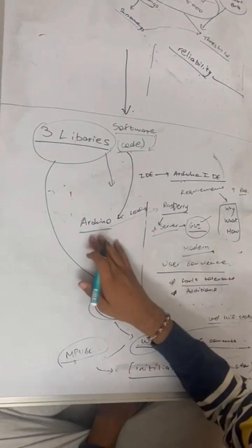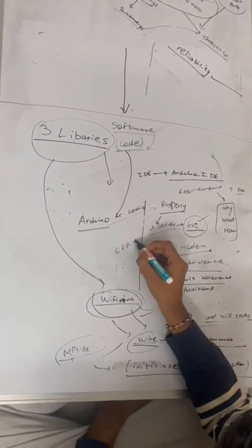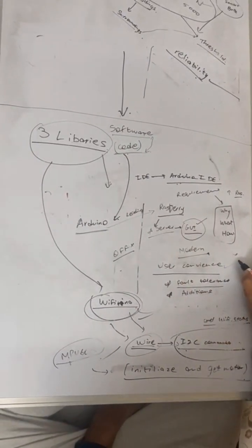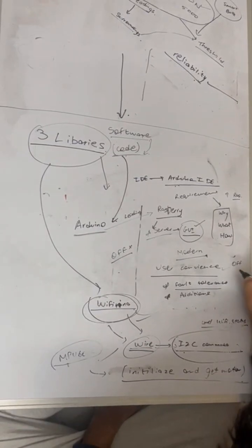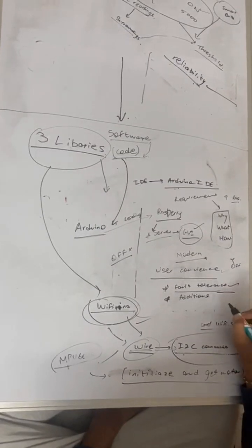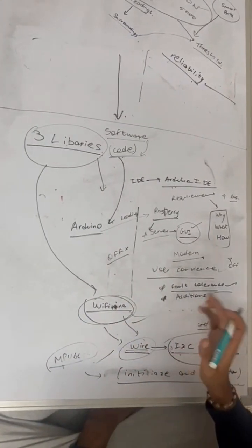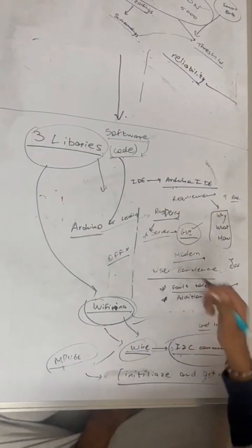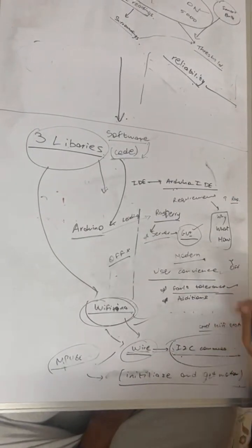For example, if the Arduino Nano is not working and the bulb is not turning off, then the user can just open the server and turn the button off. They can just click the off button and the bulb will turn off. So in terms of fault tolerance, this thing is there. If the Arduino Nano is not able to get the readings from the sensor, the server is connected to the bulb through the motor driver, and it can control the bulb through the HTML page.